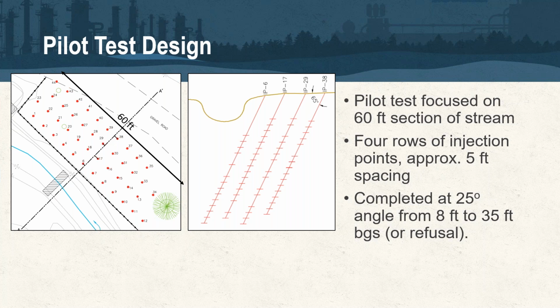Essentially, just trying to inject through a cased well is going to get caught by the filter pack and/or fill the casing that's existing there. So all the points that Mike has talked about here in the overburden scenario are temporary dedicated points. And if we're working in consolidated lithology, we do need to have open boreholes. Again, we'll get into that in more detail with the 2 follow-up presentations in a couple weeks on the bedrock installation.